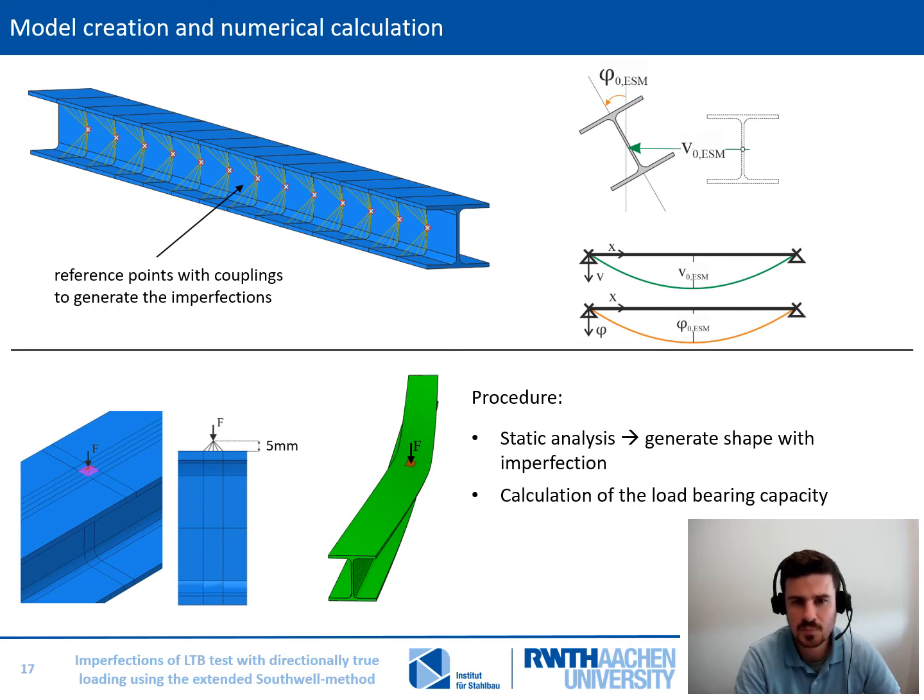In the first step, we made a static analysis with boundary conditions at each reference point to generate the shape of the imperfection. In the second step, we calculate the load-bearing capacity considering imperfections and nonlinear material behavior according to geometrical nonlinear analysis.